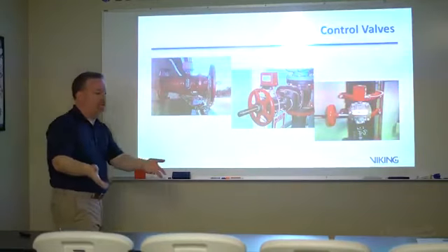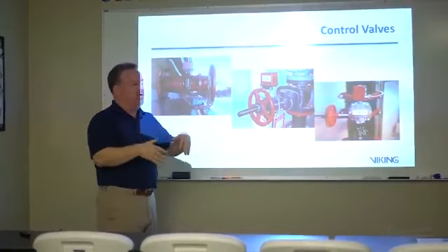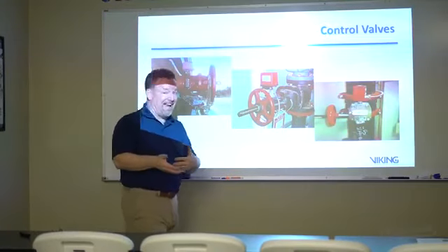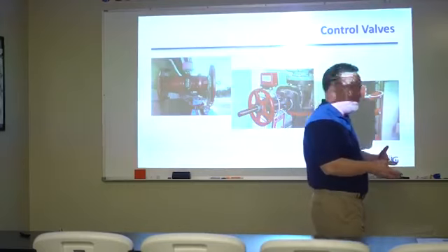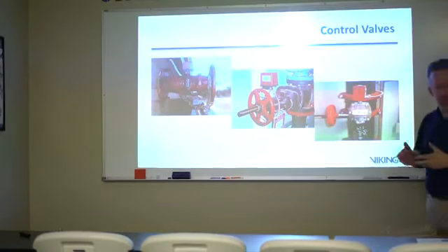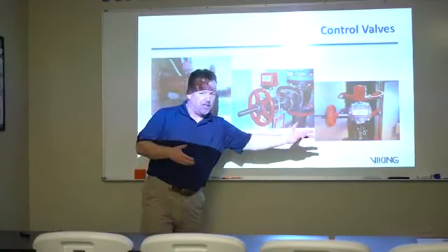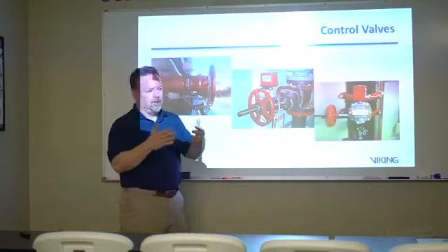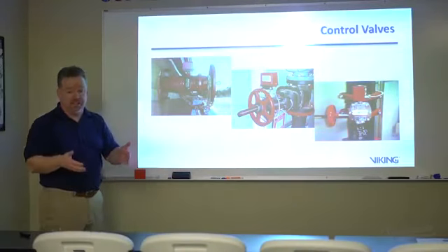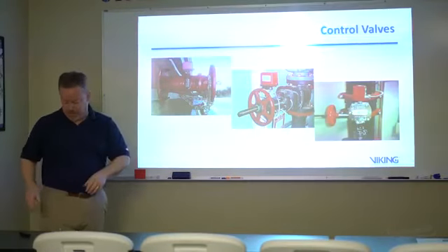The reason you want to make sure you pay attention to that, everybody, is because when I talked earlier about that 95% success rate for sprinklers, well, in that 5% of the time when sprinklers don't operate, 2/3 of that time is because a valve is closed or partially closed. So control valves become a huge focus when you're doing an inspection of an existing system. They become a huge focus. Make sure your valves are open.